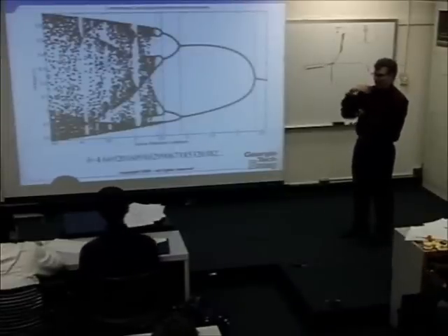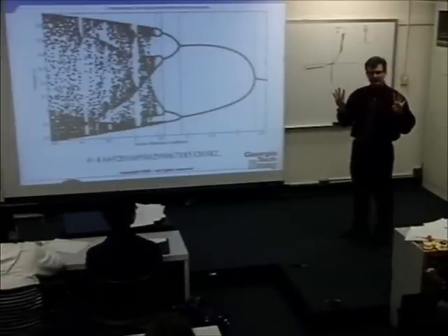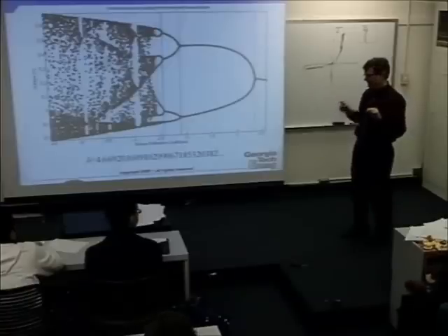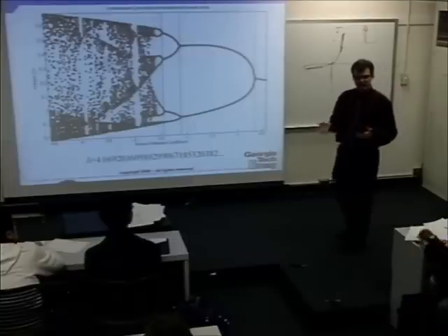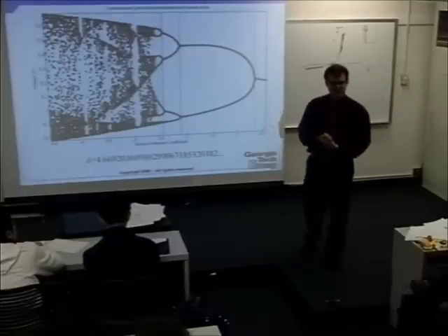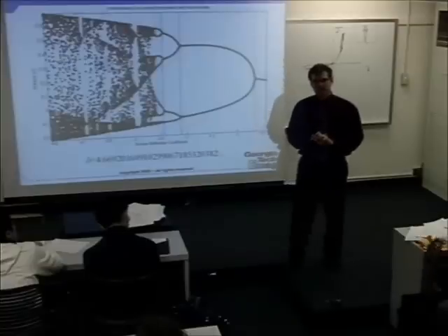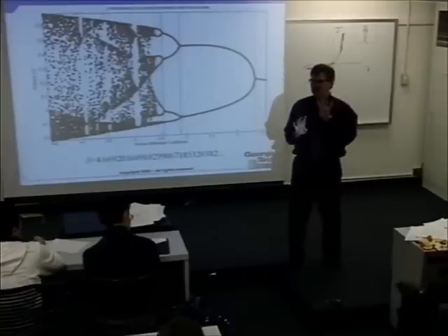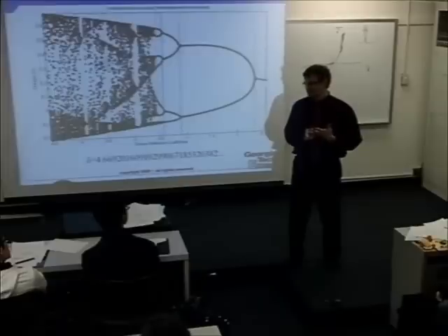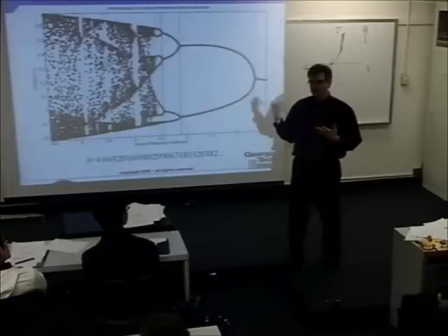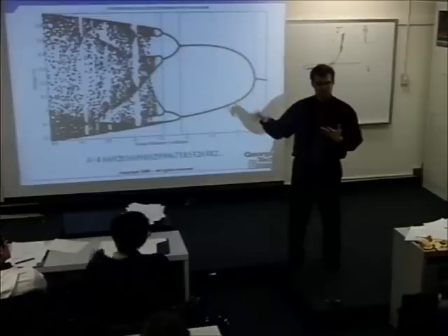There are chaotic mechanical systems. And you always need the same ingredients in electrical systems. There was a professor out of Berkeley named Leon Chua who came up with these Chua circuits. He was really the first one to show chaotic behavior in electrical systems. And he showed that the minimum ingredients, you need at least 5 elements to make a chaotic circuit. You got to have at least 3 inductors or capacitors, because chaotic behavior doesn't show up unless you have a third-order system or higher. So a little RC circuit, can't do it.